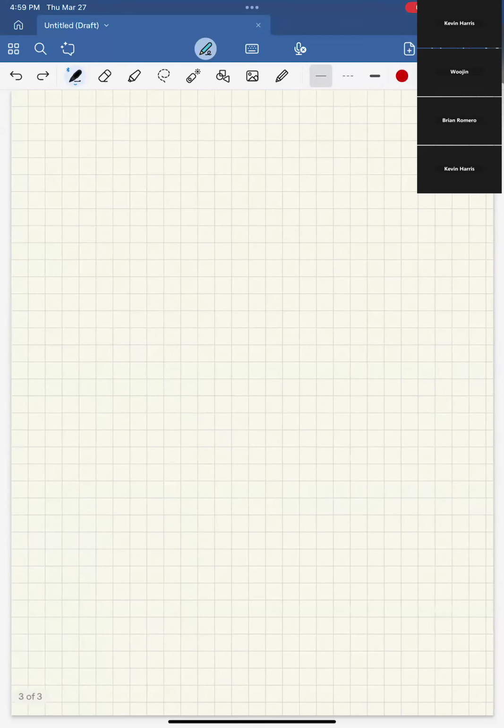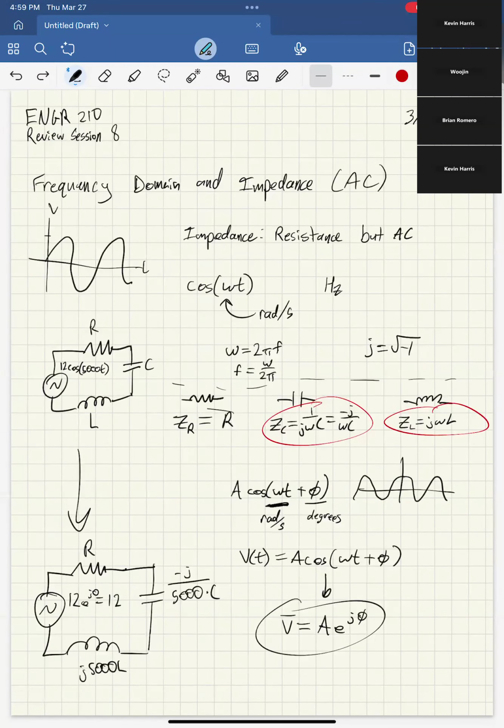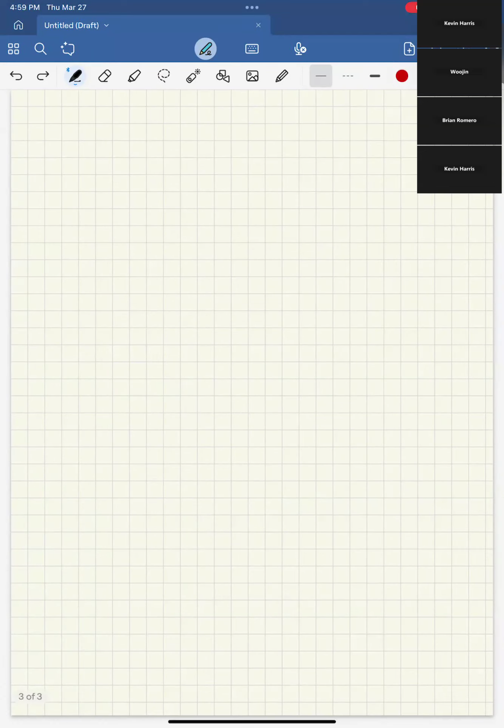Yeah, okay. Oh yeah, but then one thing I didn't say. Once you get stuff in terms of impedance, you can treat impedances just like resistances, like they're the exact same thing. If you know how to simplify a resistor circuit, then you know how to do everything in the frequency domain. So don't overthink things. It's just resistors. And this will become very clear in this question I'm about to do.